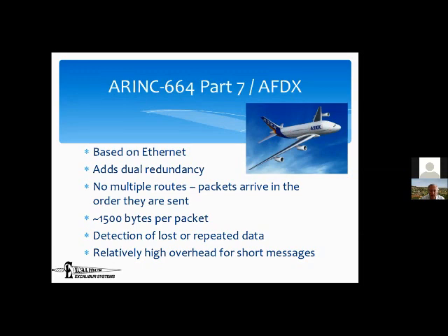and there's a huge amount of activity going into improving it, and it gets improved all the time. So they said, all right, that's the starting point, but it's not really designed for airplanes. And as two thirds of the people on the planet know, it doesn't always work, and doesn't always work quickly. That's not the sort of thing you want when you're controlling an aircraft. So the first thing they did was add dual redundancy, right? You don't want to have one wire, as we saw before. You don't want a single point of failure on an aircraft. So there's always dual redundancy on ARINC 664.